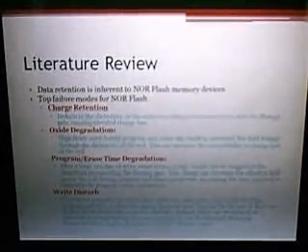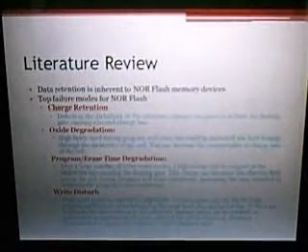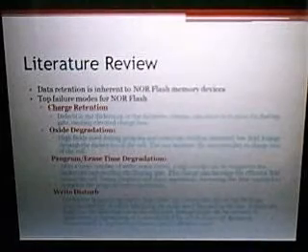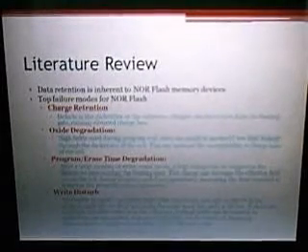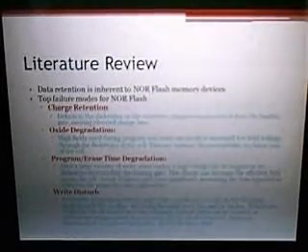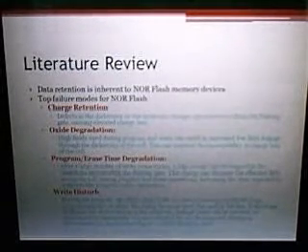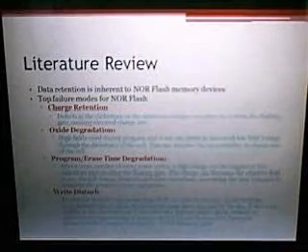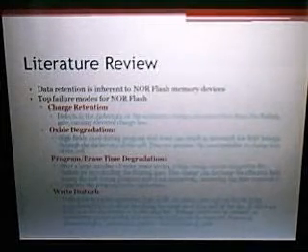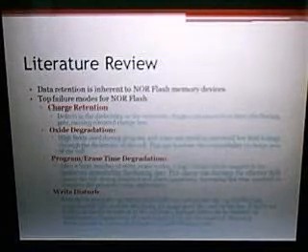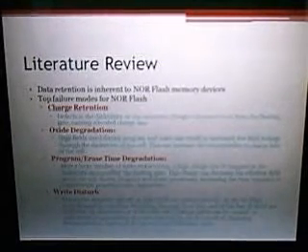This is data that we found from a Samsung Semiconductor application report on NAND memory from 1998. In this particular failure mode, although it does contain defects in dielectrics, which is some of what we're studying here with company XYZ, we can see that the data that we have is not a write disturb failure mode.